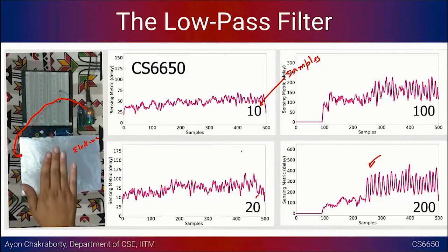Mind that we are not touching the electrode per se. It's just based on proximity sensing, very similar to the way we were using the IR sensor. When we put our hand very near to the IR sensor, we could detect this kind of thing. But as you see, this solution is way cheaper than that. We don't have any IR sensor or any other complex sensor for that matter. The only thing that we have is a high resistor, and the rest of it is a cardboard with an aluminum foil wrapped around it.